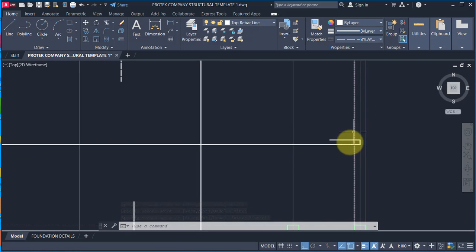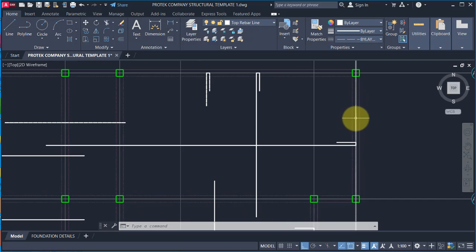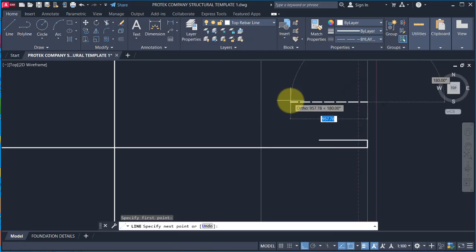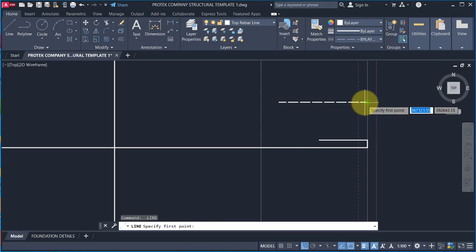Okay, so for this, we need a top bar here on this beam to be able to hold down these returns. So I'll pick a line there. I'll get a top bar of length, what was the length we calculated? 1100 we calculated earlier to be the length. Enter. All right, so for the return you go this way, 100, enter.